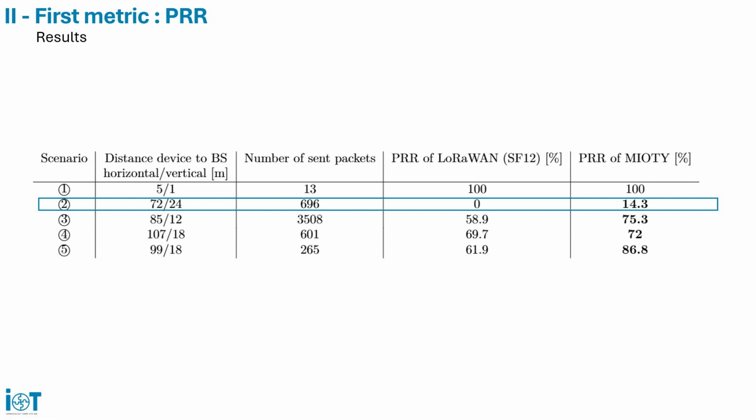There is packet being received. So the end devices, the end nodes from LoRaWAN sent packets to the base station. And then the base station, I assume the packets were thrown and ignored because they do not make sense. They are corrupted or they have a bad RSSI. So they couldn't be seen in the user interface part.